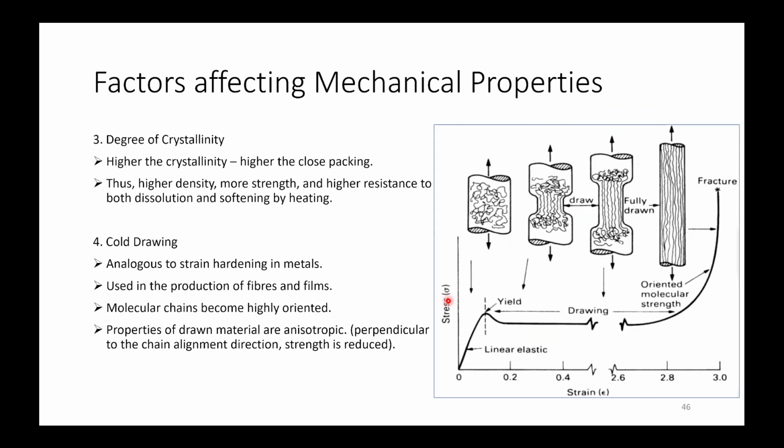Now, another factor is degree of crystallinity. The higher the crystallinity, the higher the close packing. If crystallinity is there, close packing will be there, so high density will be there, and more strength, and higher resistance to both dissolution and softening by heating.